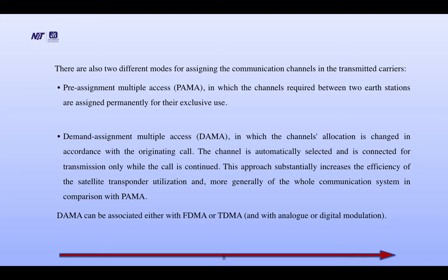The channel is automatically selected and is connected for transmission only while the call is continued. This approach substantially increases the efficiency of the satellite transponder utilization and more generally of the whole communication system in comparison with PAMA. DAMA can be associated either with FDMA or TDMA and with analog or digital modulation technique.